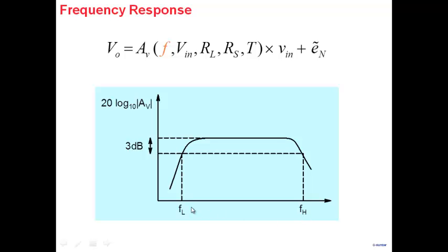of the amplifier. So this is the bandwidth over which your amplifier would work fine. Its gain would be independent of frequency. If you go beyond that, gain would be frequency dependent and gain would start falling. So besides the mid-frequency gain, we've identified two other parameters, FL and FH, lower cutoff frequency and upper cutoff frequency, or a difference of the two, which is the bandwidth. So bandwidth of an amplifier is another very, very important parameter besides the mid-frequency gain. Okay, bandwidth here.